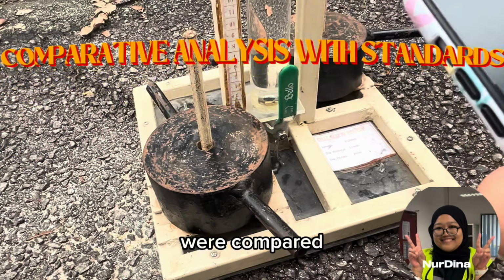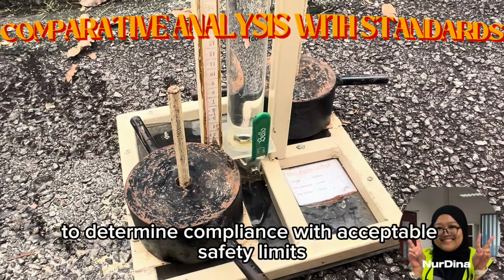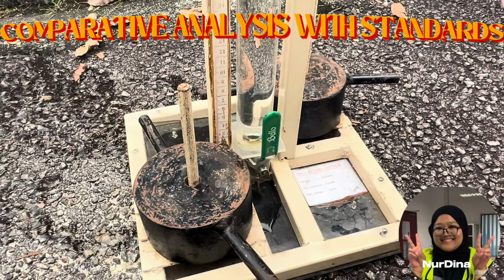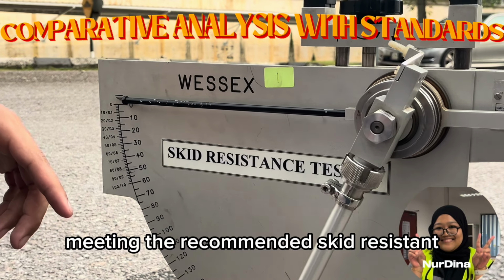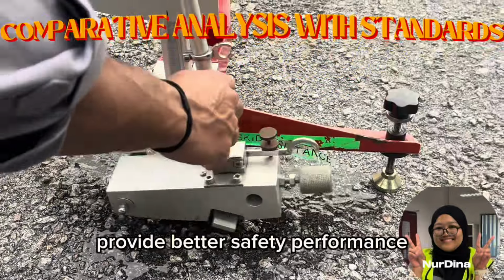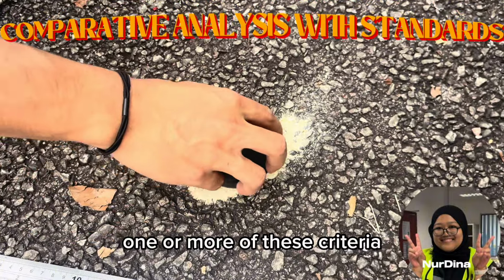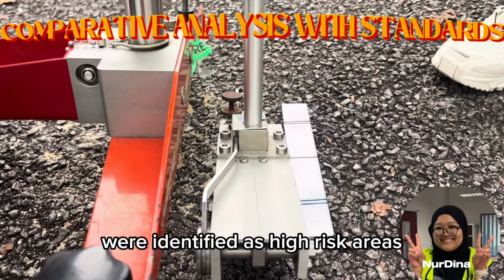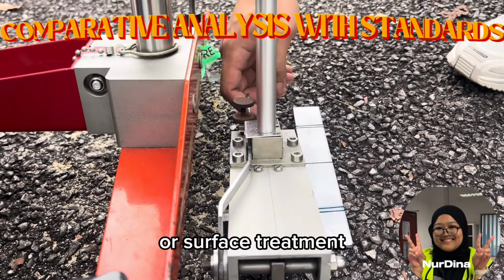All test results were compared with relevant design and performance standards to determine compliance with acceptable safety limits. The comparative analysis demonstrates that pavement sections meeting the recommended skid resistance, texture depth and permeability criteria provide better safety performance. Sections that fail to meet one or more of these criteria were identified as high-risk areas requiring improvement through maintenance or surface treatment.